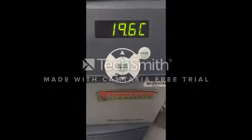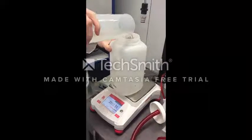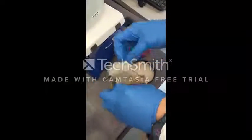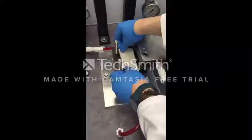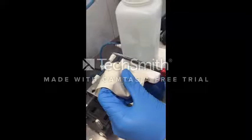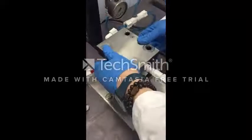Set the temperature of the chiller. Fill both the draw and feed tanks with 2 liters of DI water. Attach the quick-release tubing to the appropriate ports. Select a forward osmosis membrane, such as a thin-film composite membrane. When installing the membrane, it may need to be trimmed in order to fit the cross-flow channel. Ensure the membrane fits appropriately before securing the membrane cell.